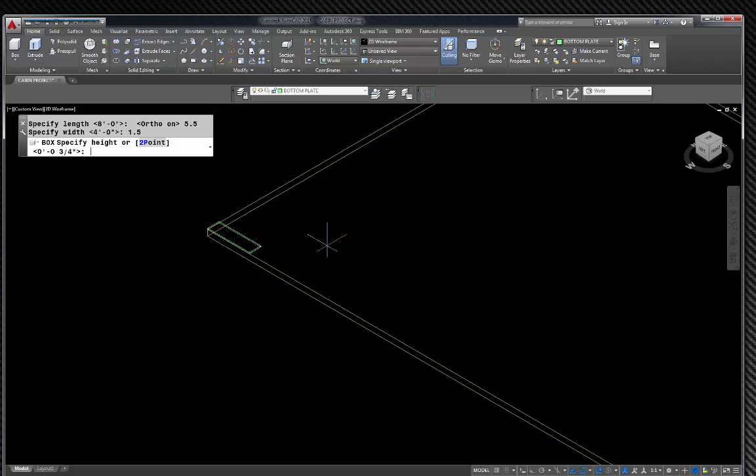And so 2x4s come in all kinds of different heights. Standard is 8 feet, okay, which is 96 inches. And they also make a 93 something, which has to do with the interior of whatever you're going to do and whether you're going to use sheetrock, and if you want the 8-foot sheetrock to work the most efficiently. For what we're going to do, let's just use 96. It's a lot easier, okay?